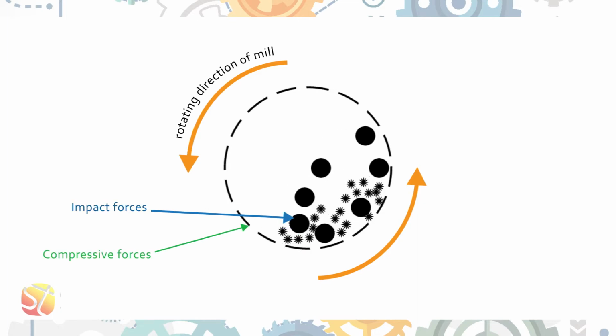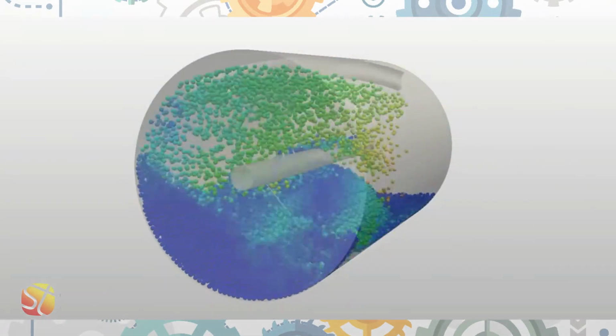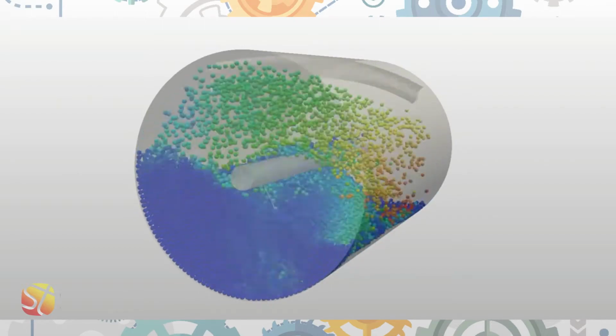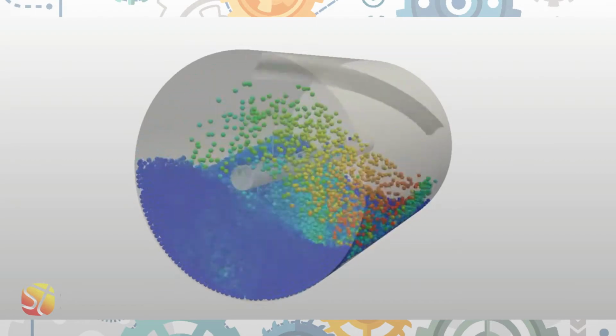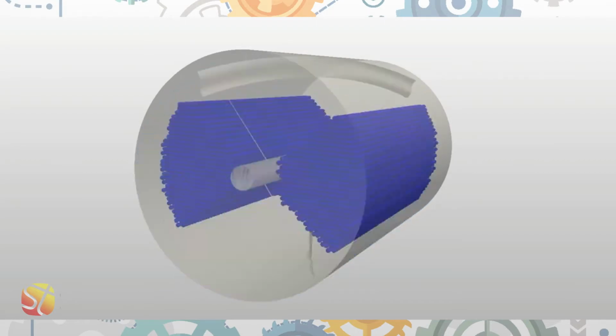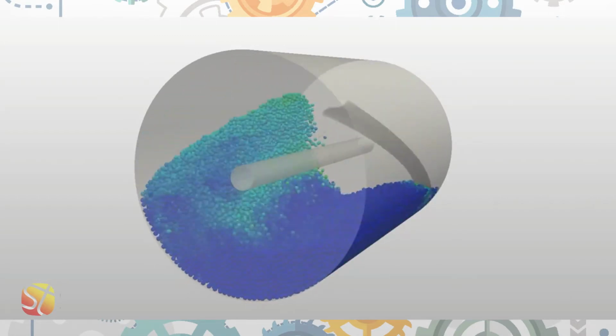You may ask them whether, do we want the particle to cascade or centrifuge? The answer, we want our material to cascade and not to centrifuge. Otherwise, the material will simply stick along the milling machine's inner shell without experiencing any form of breakage or size reduction. If it simply sticks, such a waste of energy, isn't it?